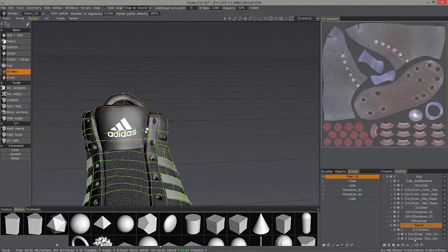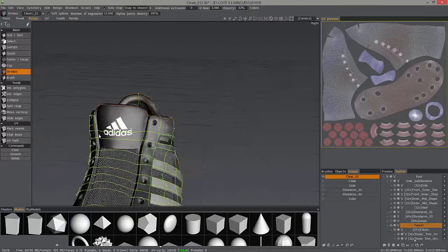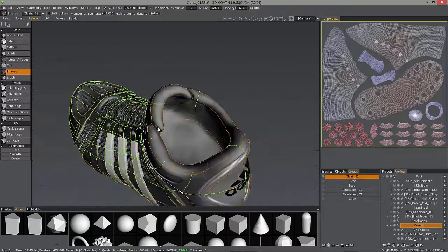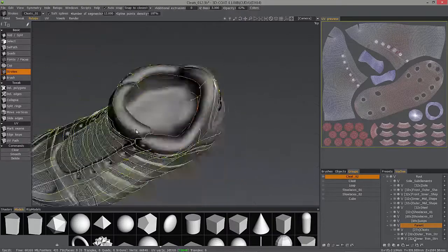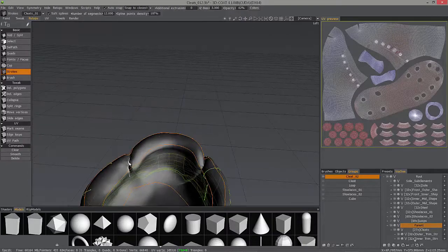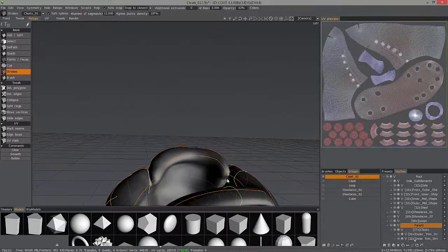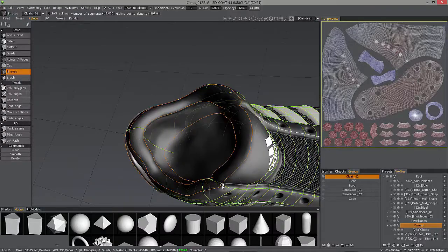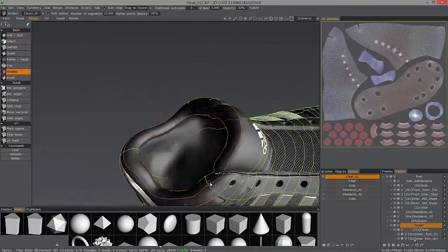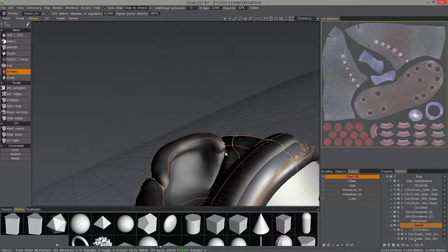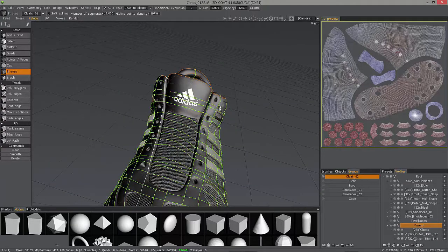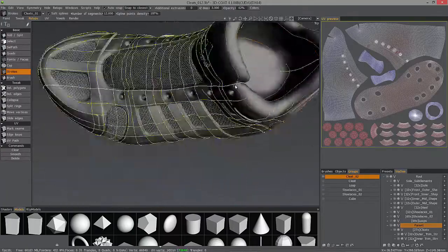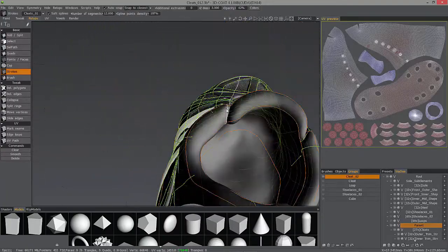And I also want to point out that a good housekeeping way to keep your mesh nice and tidy when you merge a copy like that is to right click on that layer and choose fill voids, because anytime you do a merging operation in Voxels, sometimes you may find that it leaves you with some small little bubbles or voids inside the voxel structure.